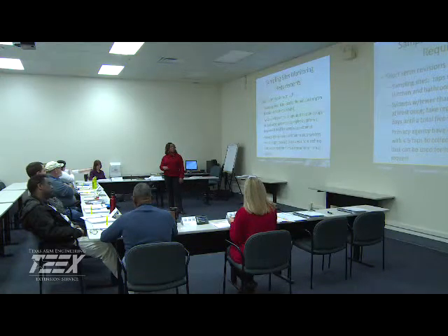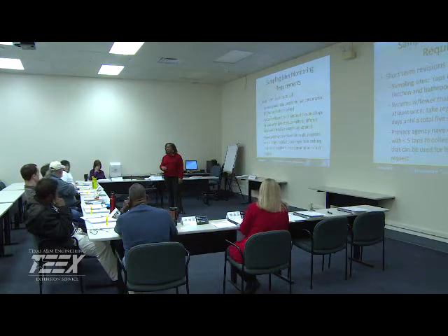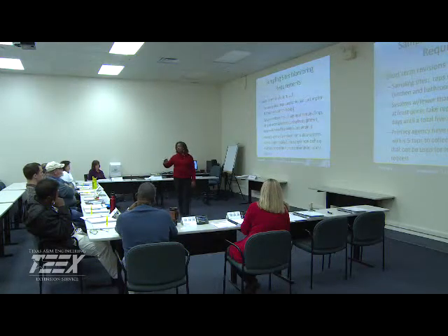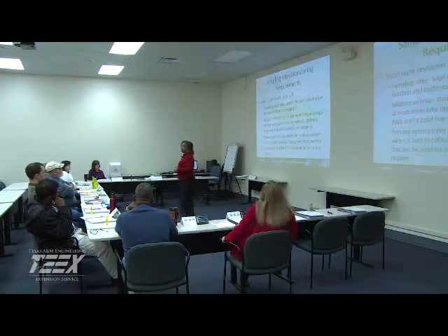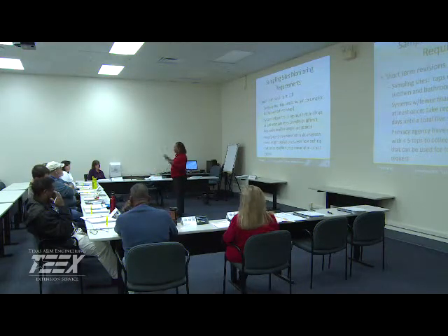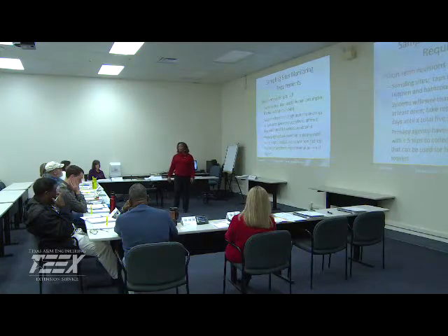5 taps in one place, in one person's home? No, in the distribution system. So we're talking about a public water system: community water systems or your non-transient, non-community water systems. Remember, that's what lead and copper is applicable to. So not individual homes. Although in the islands, most of their systems, in some cases, were just individual homes because it was all rain capture with the one sample.